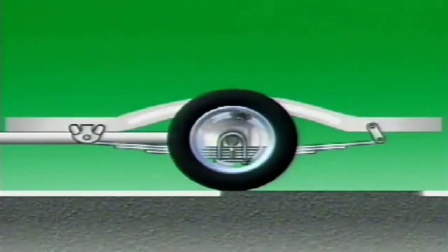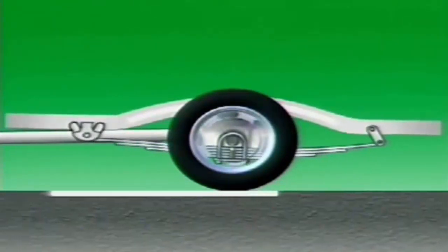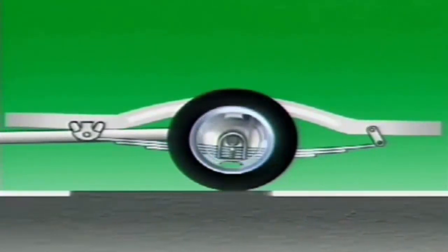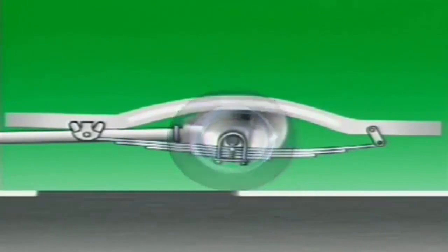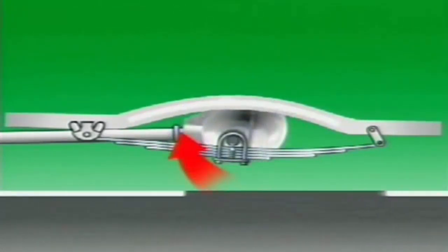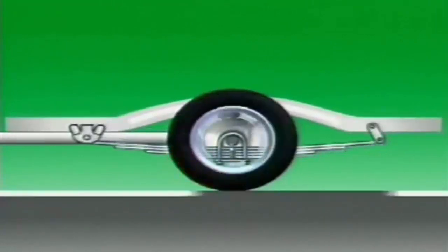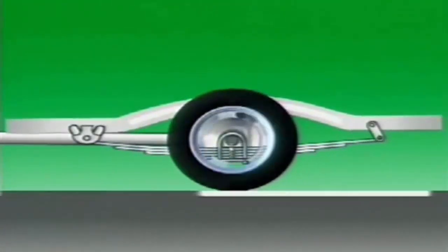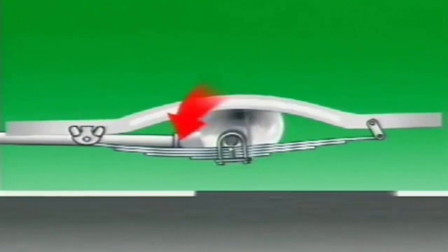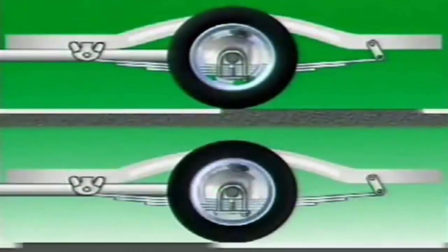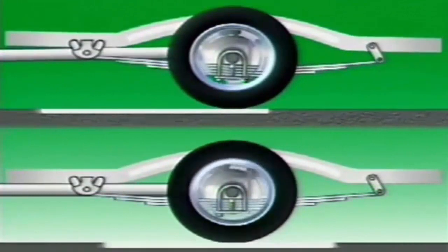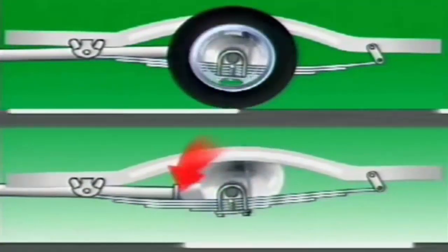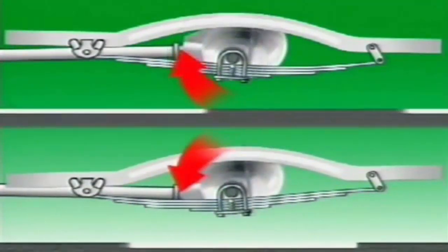When a vehicle accelerates from rest, the resistance of its mass causes a torque reaction, producing a tendency for the axle housing to rotate in the direction that is opposite to wheel rotation. A similar effect occurs during braking, but with the twisting effect in the direction of wheel rotation. In both cases, this tendency can cause leaf spring wind-up, and the twisting action can interfere with suspension motion.